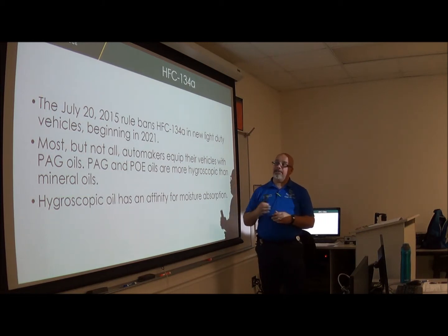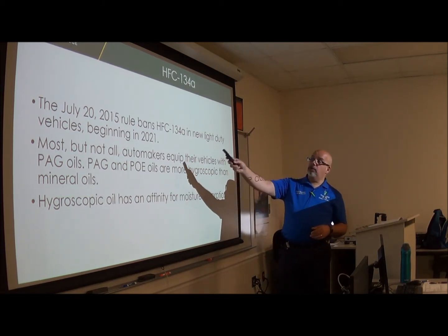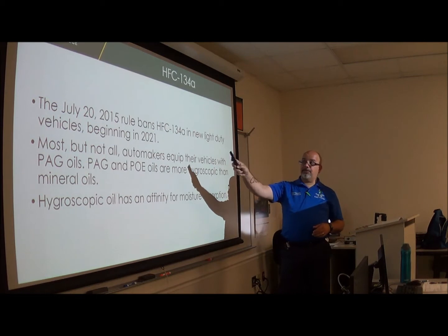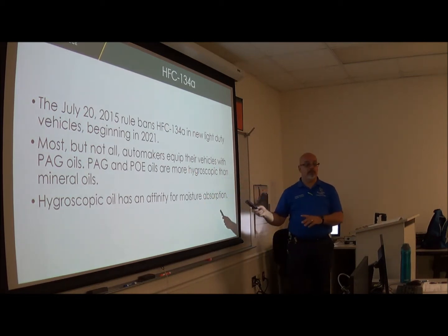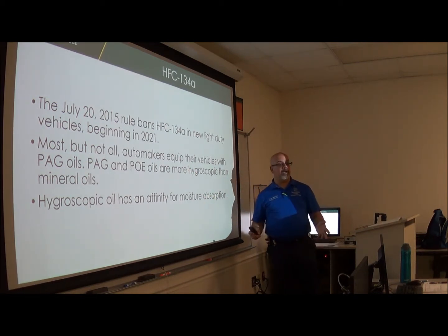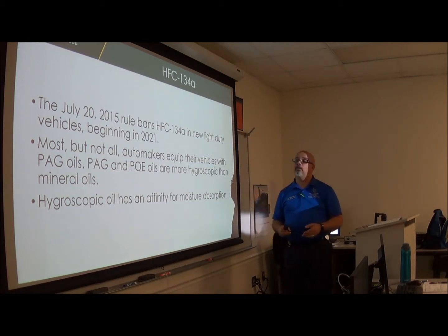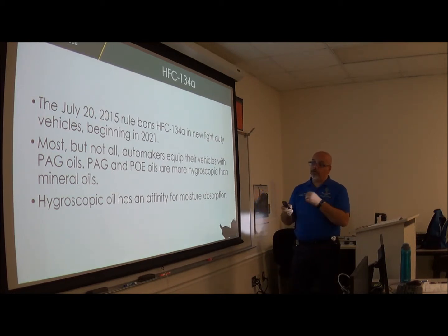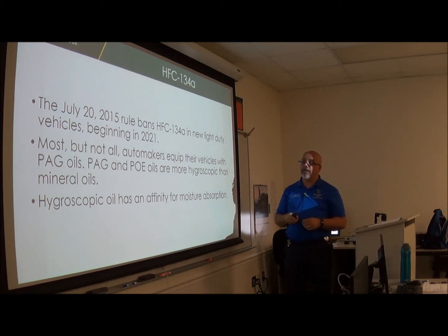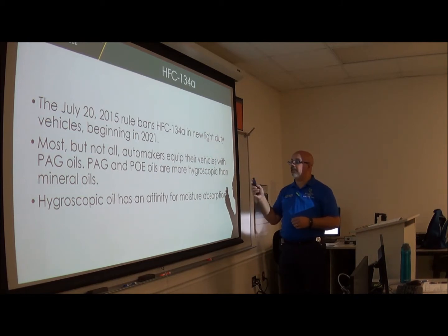The rule from July 20, 2015 said that by 2022 all the vehicles had to have 1234yf. Most but not all automakers equip their vehicles with PAG oils. PAG and POE oils are more hygroscopic than mineral oils.